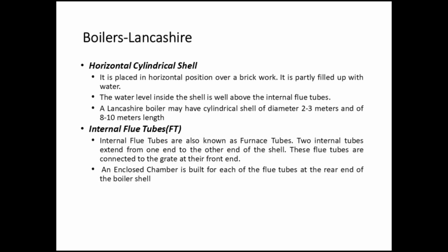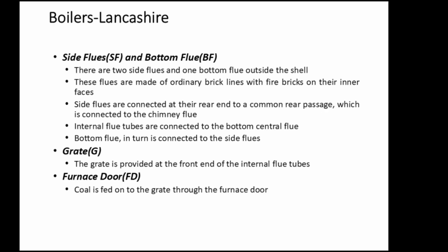Internal flue tubes. Internal flue tubes are also known as furnace tubes. Two internal tubes extend from one end to the other end of the shell. These flue tubes are connected to the grate at their front end. An enclosed chamber is built for each of the flue tubes at the rear end of the boiler shell.